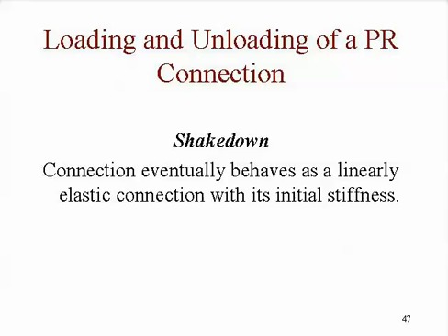Now there's a major concern when you get to this point. And that is, remember that connection that I showed you that went way up that curve, looked just like this curve, and then there was a bolt failure? Most of the model equations make it appear that the connection just goes on forever. They're just equations. They don't say, okay, it ends here. And we have to be careful when we design any of these connections to make sure they behave the way we're expecting them to behave.